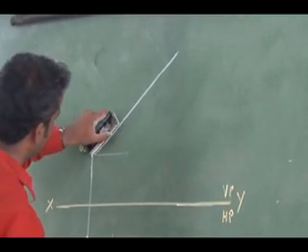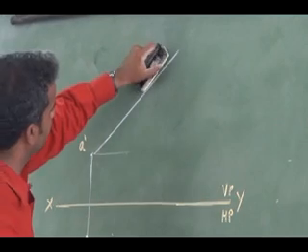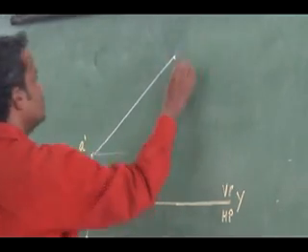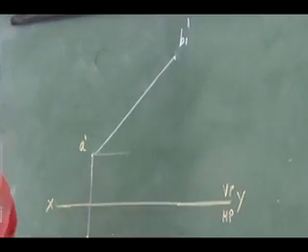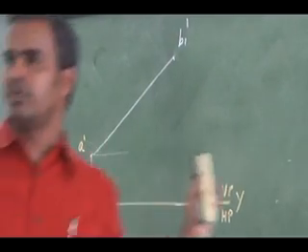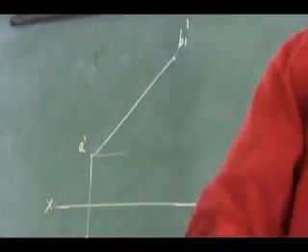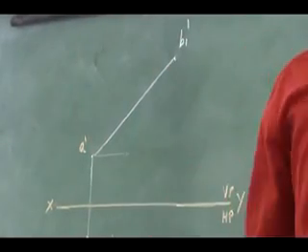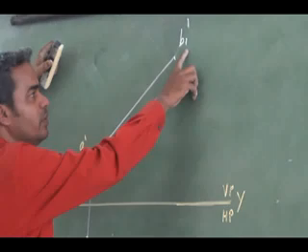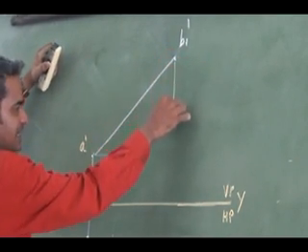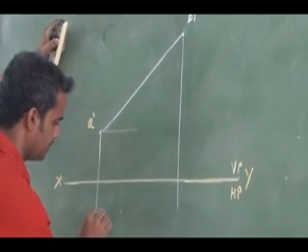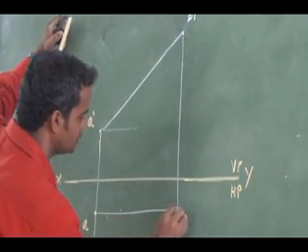So this will give me the 75. This is my B1 dash. These notations are very important. Once you have drawn, you have to mark the notation then and there, otherwise you will get confused. So B1 dash, the first assumption. Then, by projecting this, I will have my top view in the first assumption.